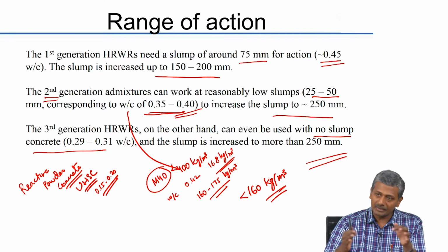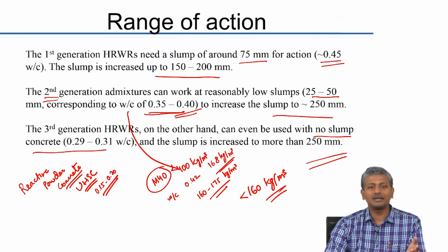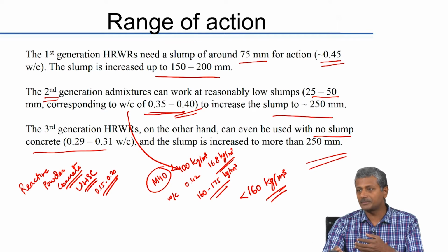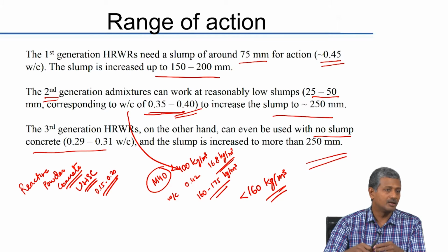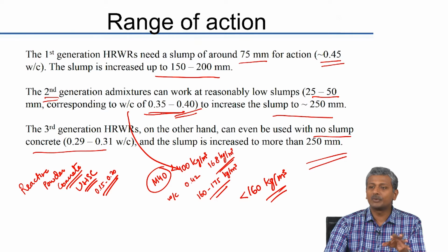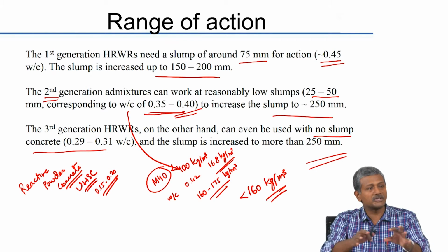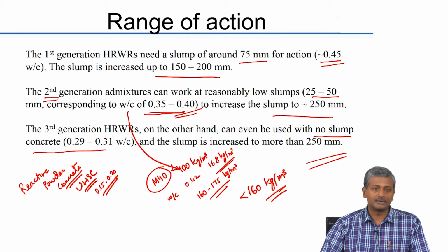Most of the water is added in the beginning itself without the superplasticizer, and all that is done primarily because of that issue we talked about earlier, that the C3A needs to react with the sulphate from the cement before the sulphate from the superplasticizer comes into the system. Okay. So, superplasticizer is added with the remaining part of the water into the mix. And when it is added with the water, the dispersion of the SP across the entire volume of the concrete is automatically ascertained.